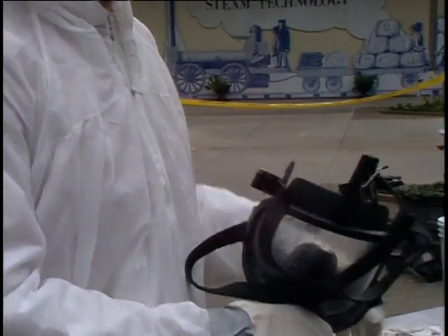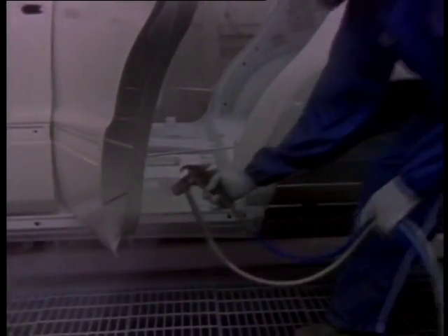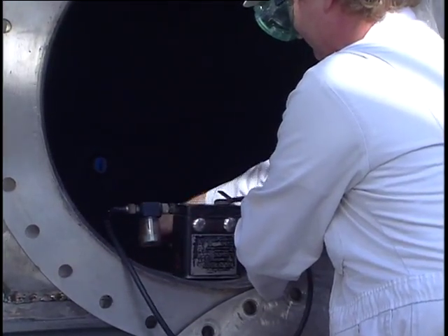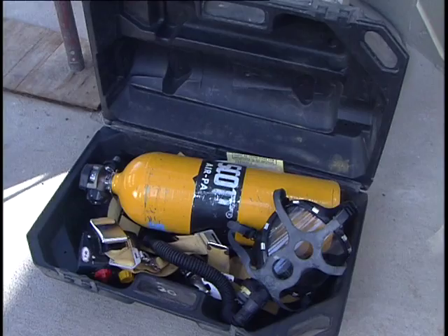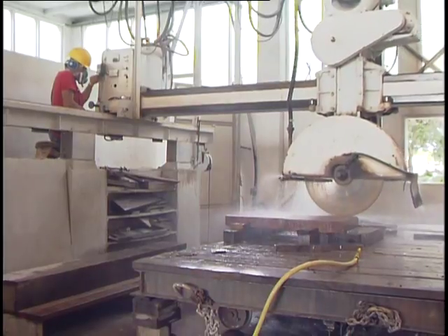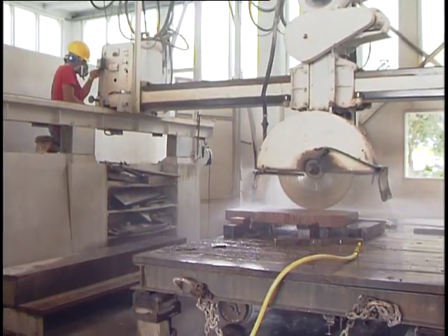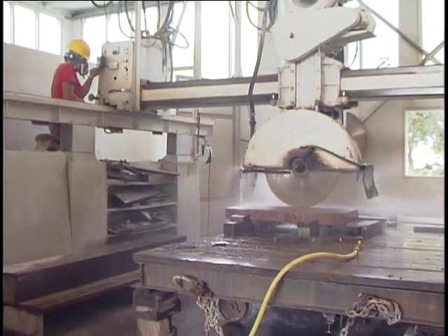Many factors must be taken into consideration when selecting respirators. Workplace factors are very important to consider when it comes to respiratory selection. Constrained or tight areas may not permit the use of a self-contained breathing apparatus, even though it might be an acceptable choice. Likewise, working around obstructions or moving machinery that can snag hoses may limit the use of airline respirators.